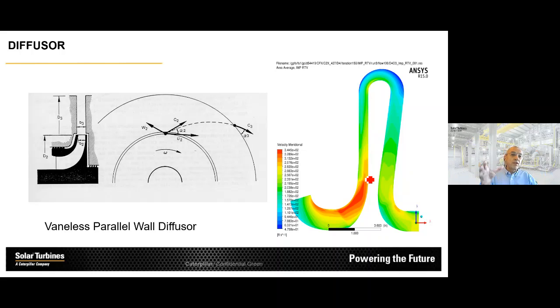So the compression process is a two-stage process. I enter all the energy into the gas in the rotating part, but what comes out of the rotating part has a higher pressure, but also a higher velocity. And then in the stationary part, I convert a lot of that velocity into more pressure.